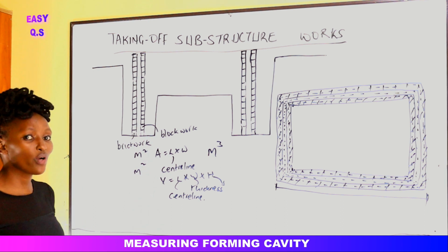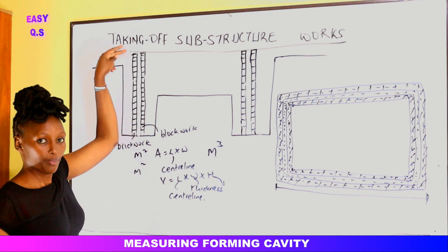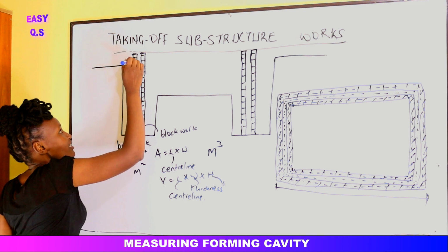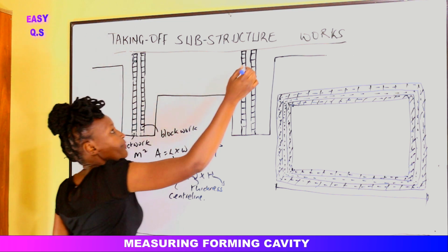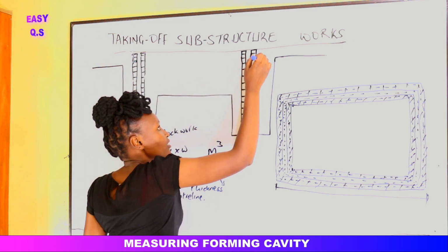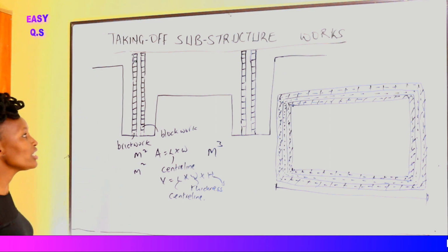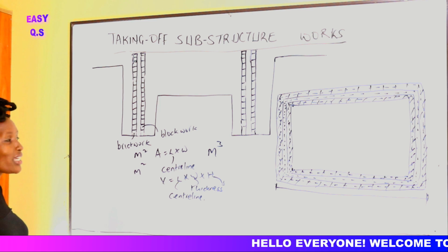So we usually do an adjustment now that we had already calculated the brickwork up to the top here. But these bricks which are here and here, if this is the ground level, they are on top of the ground, so they are facing bricks. We need to do some adjustment, some change to the brickwork that we had taken off.